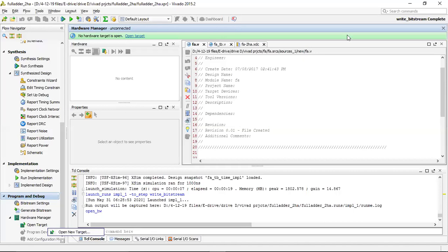So with this step, I will conclude my presentation here. How to simulate, how to synthesize and how to implement on FPGA, we have discussed everything, and how to find out the power consumption, and how to find out the timing between input to the output, that is the propagation delay, using this tool. So we have discussed everything, pre-synthesis, pre-simulation as well as post-simulation also discussed here.